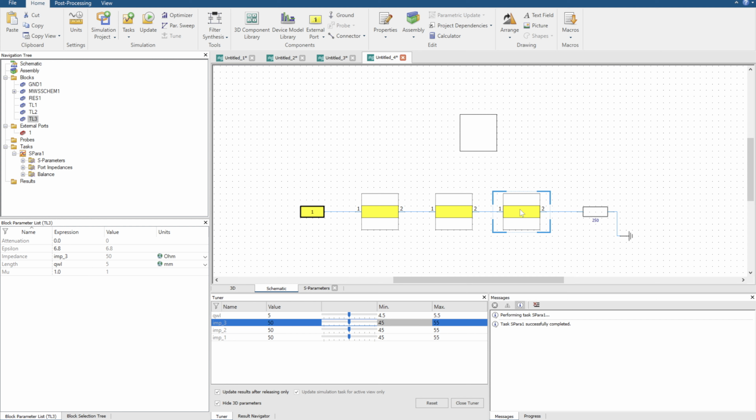And if you go back to some famous textbooks, either Pozar or even further back, there's one called coupled line networks that's going to tell you exactly, from a wideband impedance matching network table, what each impedance needs to be, and it will work perfectly every time. However, if you don't have access to that, or you just want to see what the impedance values do to the Smith chart or to your S11 response, now we can kind of just play around with the values. So I'm going to set a max value of 250 for every single one of them. And I'm going to set a value of 50 as the minimum for every single one of them.